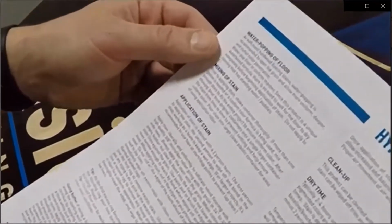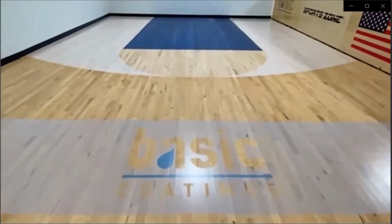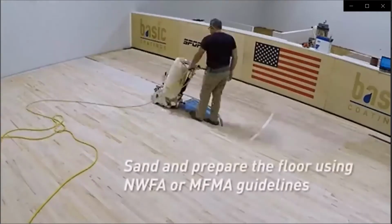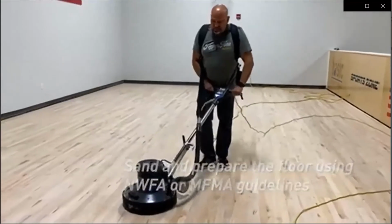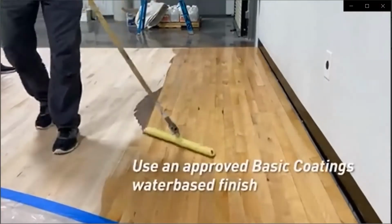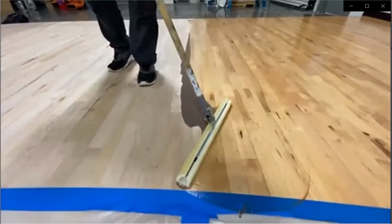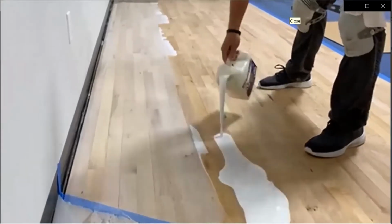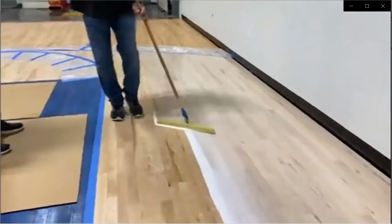You can use HyperTone stains to tint approved Basic Coatings water-based finishes for sand and finish work, as well as screen and recoat jobs. Prepare the floor using NWFA or MFMA guidelines for sanding and/or screening. When using HyperTone stains as a tint, use only in specifically approved Basic Coatings water-based finishes. A complete list can be found in the HyperTone Stains Technical Bulletin. Wood flooring needs to have at least one coat of an approved Basic Coatings sealer before applying tinted finish. Allow the sealer to dry per instructions on the label.